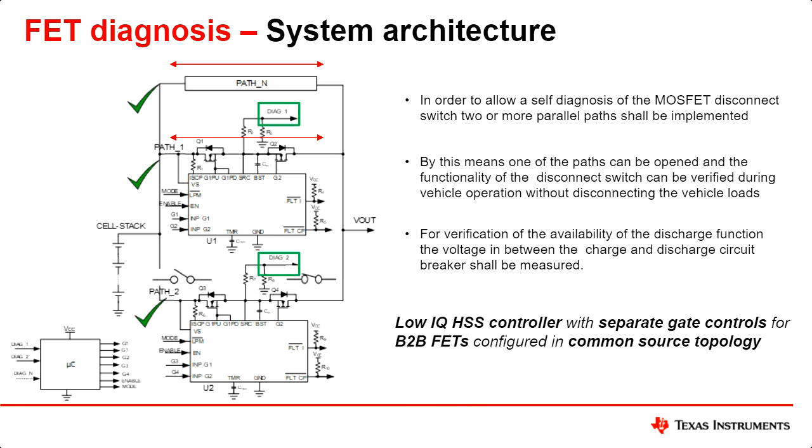So essentially, the ask here for a BMS system is to have a very low IQ controller with independent control of the charge and the discharge FET, configured in a common source topology, which also supports low side current sensing based overcurrent protection.